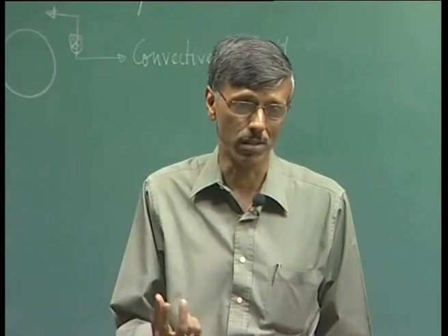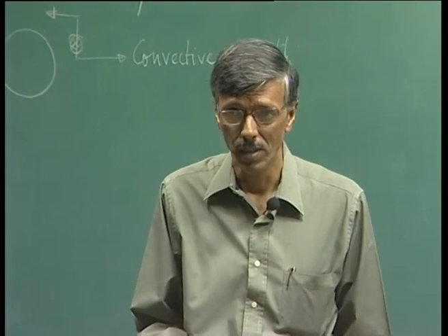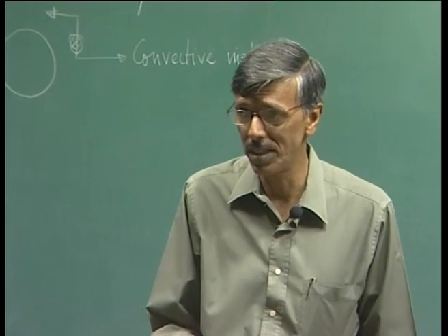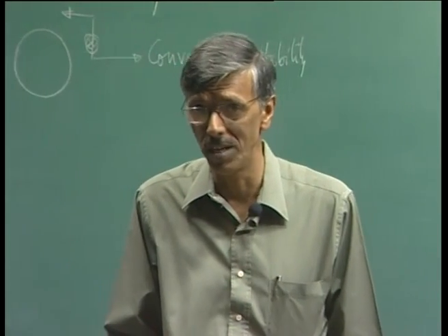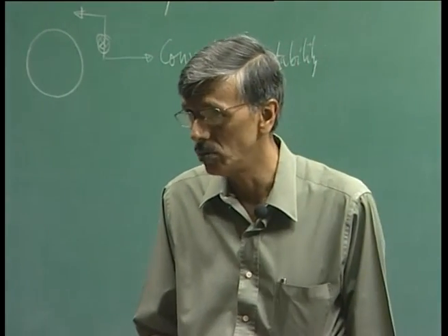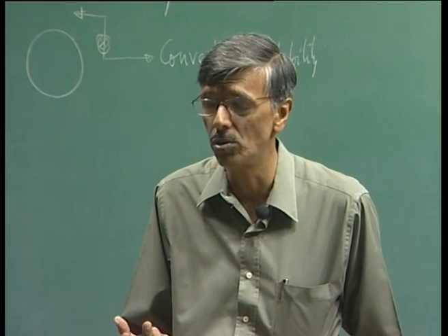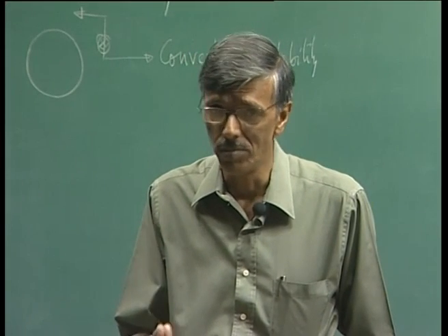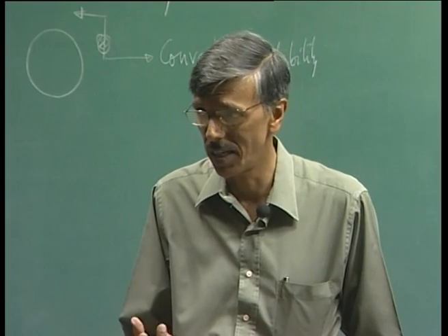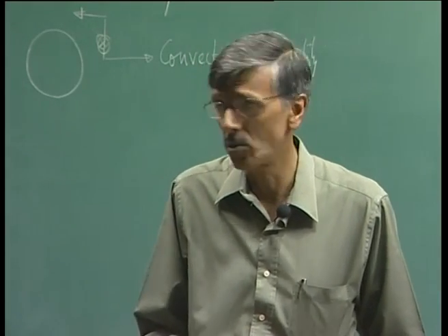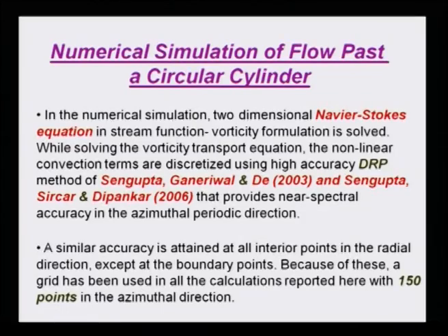Conservation principle of what? Conservation of mass. If I solve, say, the Navier-Stokes equation in primitive variables, you know that it takes a lot of effort to preserve the mass conservation correctly. That actually is quite time consuming.